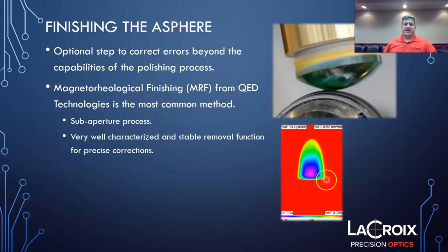One limitation it has is you can't use it for, say, grind out or smoothing, because it is a very conformable tool. So as I mentioned before, if you try to polish a ground part with this, you'll generally end up with just very shiny ripples on your part instead of removing the ripples. So you do still need those previous steps. This is not a do-all polishing tool. It's an awesome finishing tool, though.